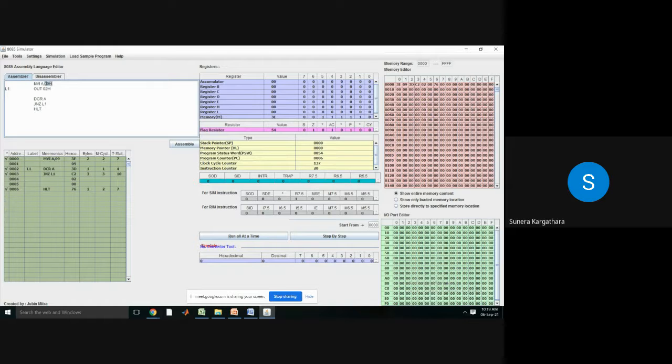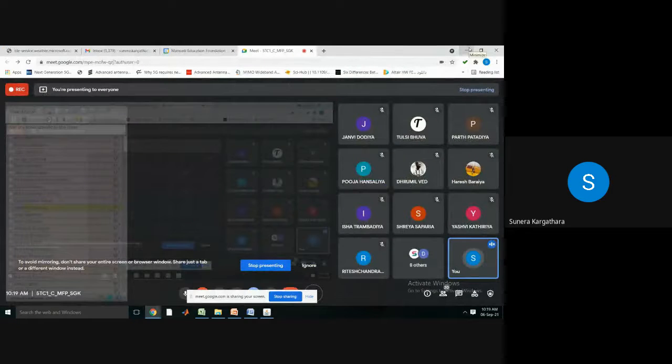The register you are taking and decrementing, in between them you put a loop, so that loop will execute depending upon the timing requirement that you need, and then it will decrement, check, and send to the output code. So a certain set of instructions you need to write in between two counts, so that will be a finite time that you will get in between two count values. Are you getting my point, student?